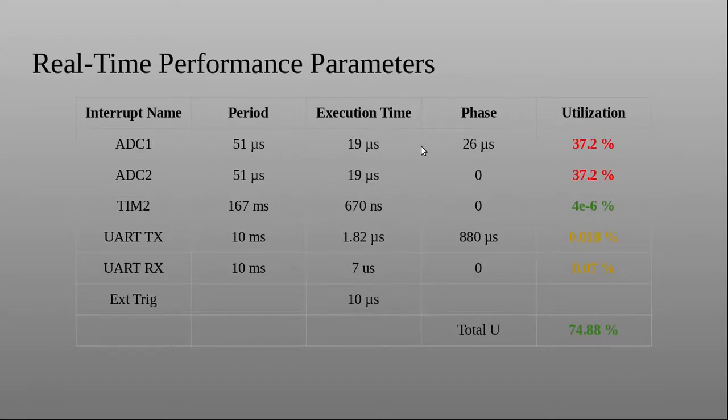Timer 2, which is basically something that takes care of temperature scanning and other housekeeping functions like toggling LEDs and also checking whether the gate driver is healthy or not. All those functions are being done by timer 2 as an interrupt, and it keeps on scanning at that interrupt rate. Then we have the UART transmit and receive, which are responsible for